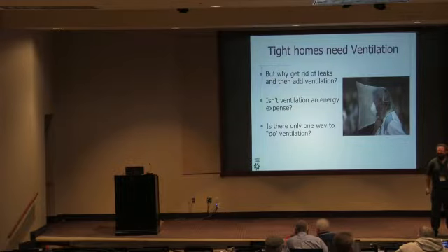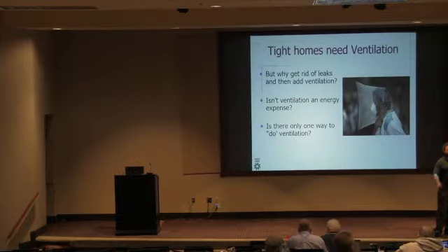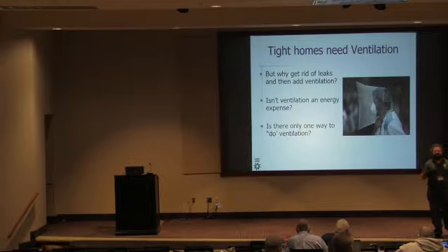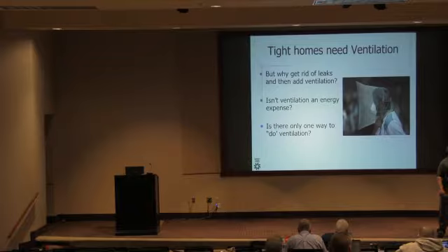Any other questions? Yeah, we see this all the time, right? Somebody renovates the kitchen, they put in a giant blower door sized fan into their kitchen, and then they blow 2,000 CFM of air out of their house, and they wonder why it smells like a chimney. Well, it's because you don't have a makeup air pathway, and you're putting your house under a ridiculous amount of negative pressure. And in fact, the IRC says, what? Exhausts over 400 CFM need to have what? Makeup air. Do you think that gets complied with all the time? On a renovation? Heck no.